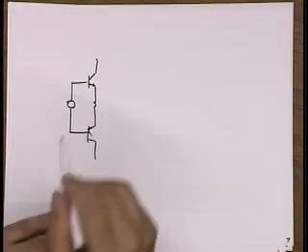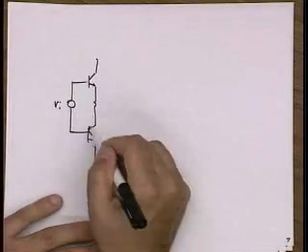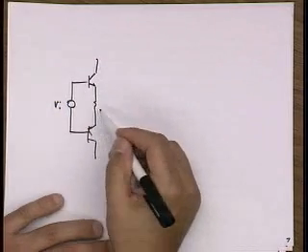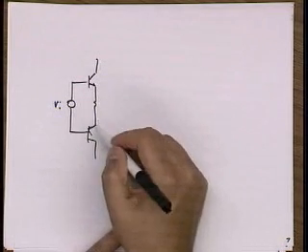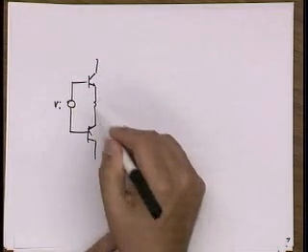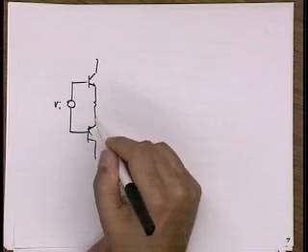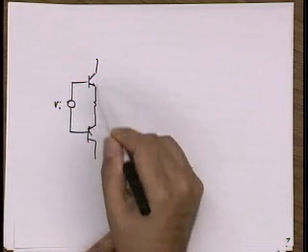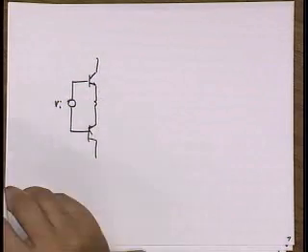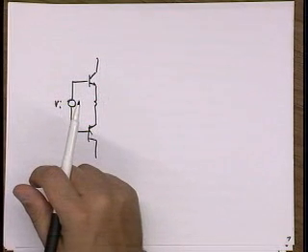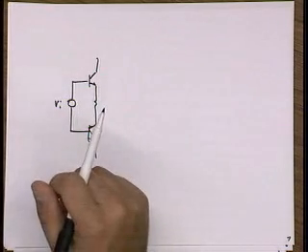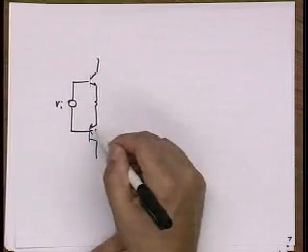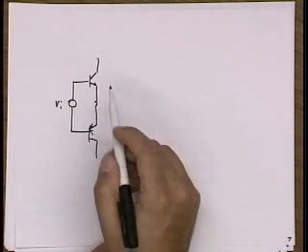So essentially, I'm taking my input voltage and applying it across a delta VBE in this R. Let's assume this R is equal to 0. Then I'm applying my V input across basically two different VBEs, right? What other circuit do you know that applies the input across two VBEs? Kind of like a diff pair, right? A diff pair does the same thing. The difference here is I'm using an NPN and a PNP.